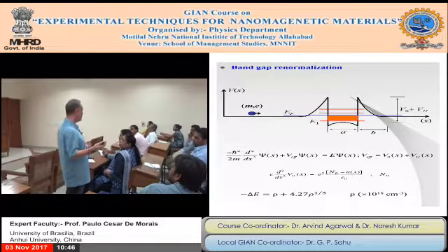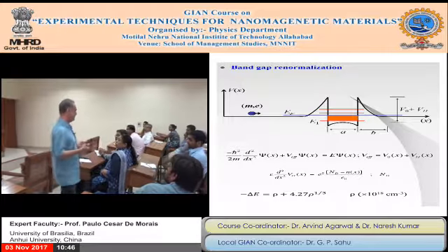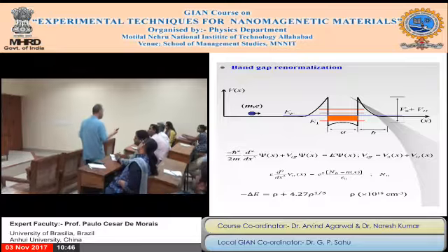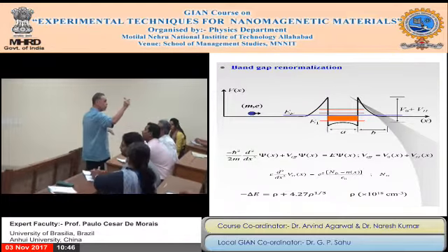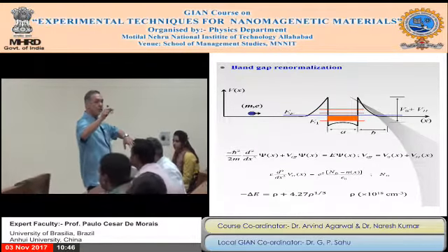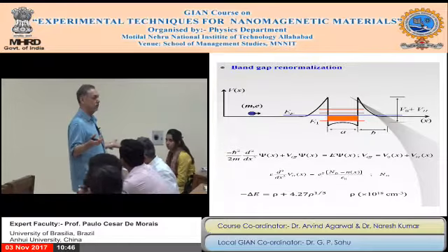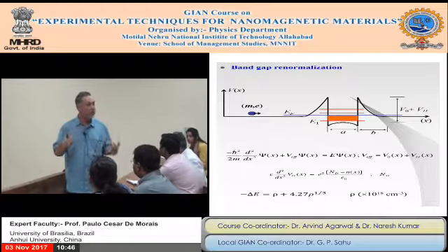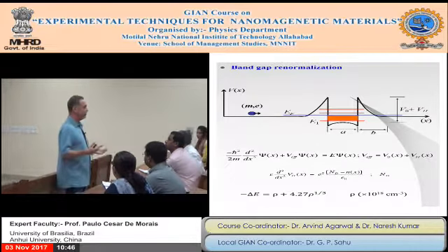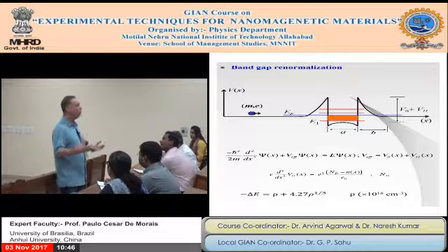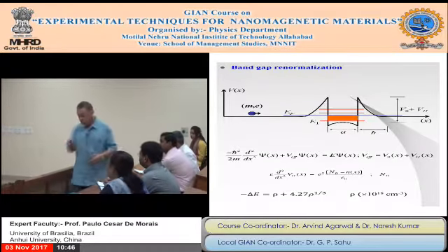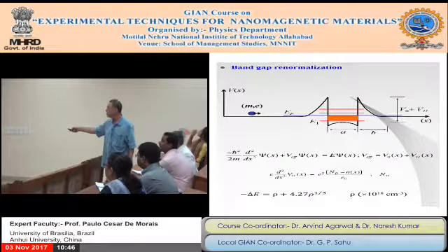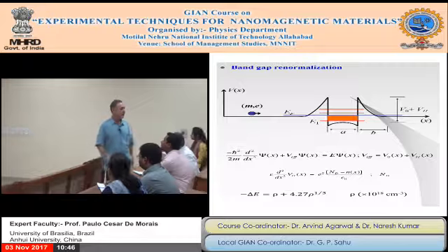We know this is called Poisson's equation. Simply like this. If you take a charge, then you just bend the potential. The derivative of this potential is exactly the density of charge. This is called Poisson's equation. So, because we took many electrons inside, then comes the Poisson equation, just bend it. It's called band bending.